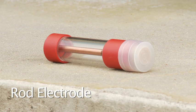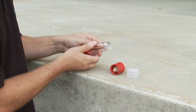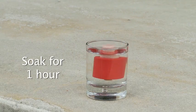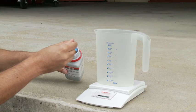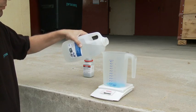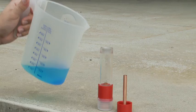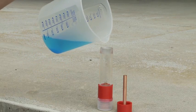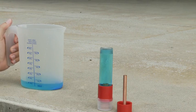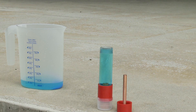Preparing the rod electrode. Before filling, remove the cap with the wooden plug and soak it in water for about an hour to allow the wood to saturate and swell and to ensure a low resistivity contact. Prepare the saturated solution by mixing 40 units by weight of copper sulfate with 100 units by weight of distilled water. The electrode should be filled as completely as possible with a minimum of air in the compartment. This ensures that the solution is in contact with the wooden plug even when measuring in an upwards direction.